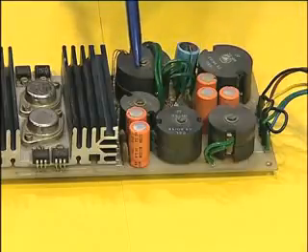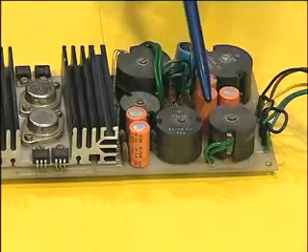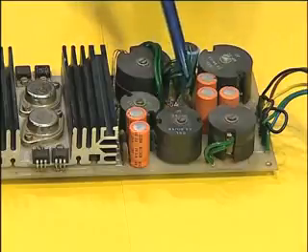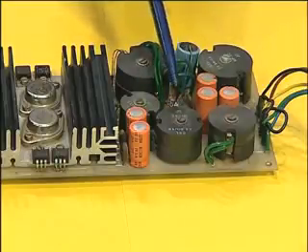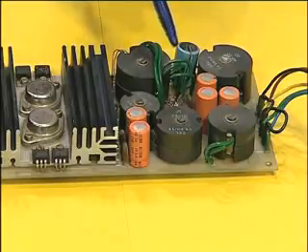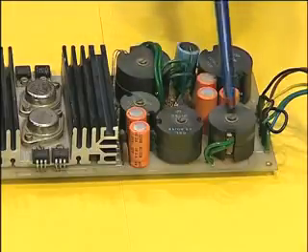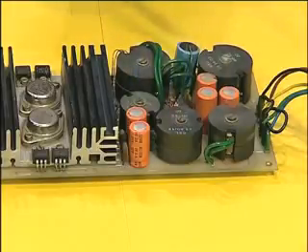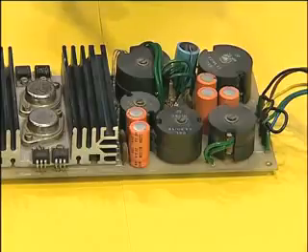They can be used for applications ranging from 20 kilohertz to 100 kilohertz, and special cores even up to 300 kilohertz and further on. If you want to use for low frequency applications like 50 hertz applications, one has to use not these ferrite material, but the silicon steel material.